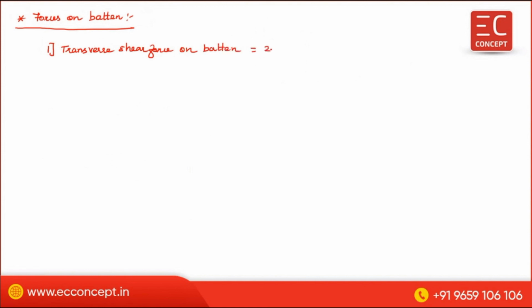So next point is forces on battens. First one is transverse shear force on batten, which is the same as in the lacing system, 2.5% of column load.